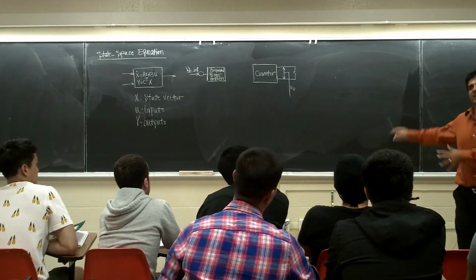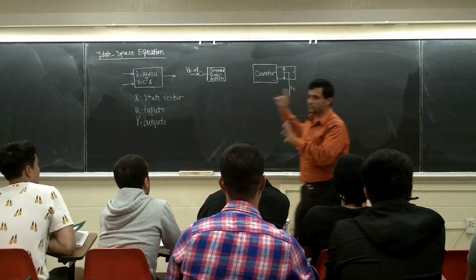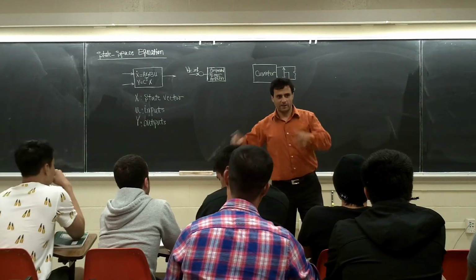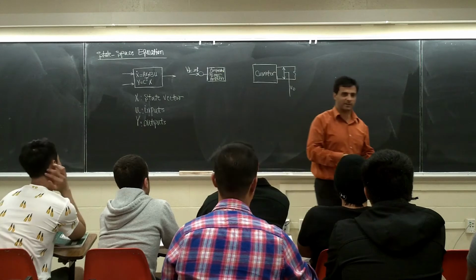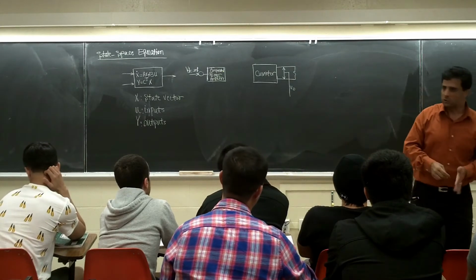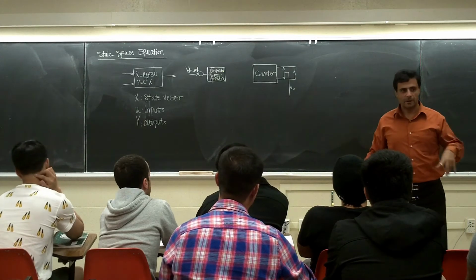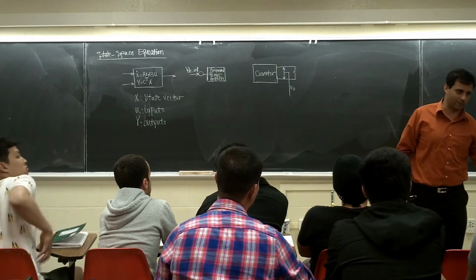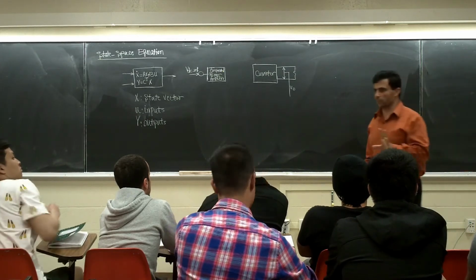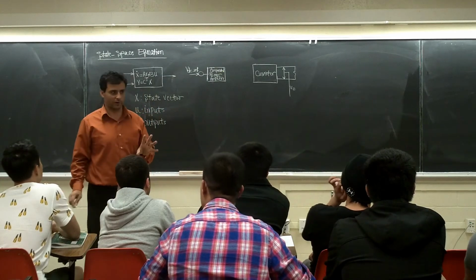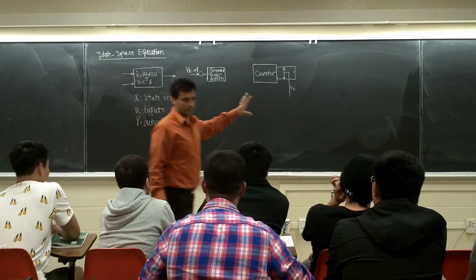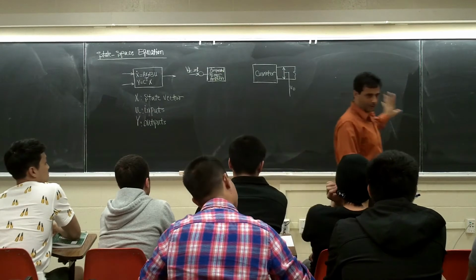The PI is in a DSP. See, this is the advantage of digital signal processing. That PI, I gave you the equation, and you can go implement it in the DSP, right? And you build that one. You don't need to build any circuit. But if you go back 20 years ago, when digital processors were not this strong, and we didn't have a good microcontroller, they used to do everything analog. Everything was analog.